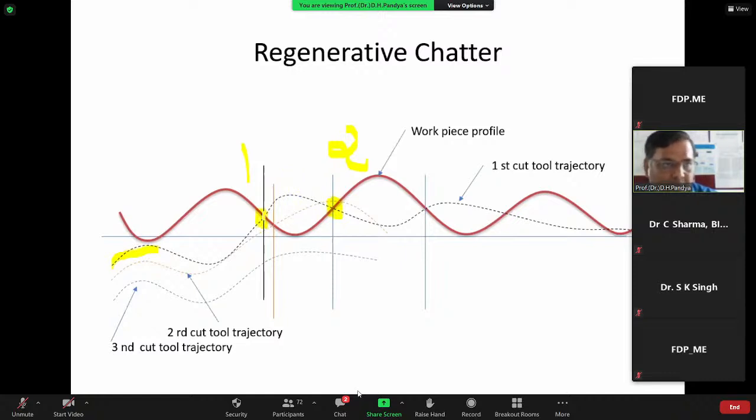The same thing will happen over here when it comes out of this material contact. There is a sudden disengagement from the workpiece, and this particular tip is going to harden a little bit, and these two points are clearly shown as a mark on the surface. We measure this as waviness, or it is a very clear chatter indication on the surface. Why is it so complicated?